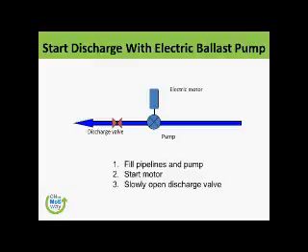This is what I want to see every one of you in the classroom. When you are starting the pump, you need to start it in this fashion: fill the pipelines, start the motor, slowly open the discharge valve.